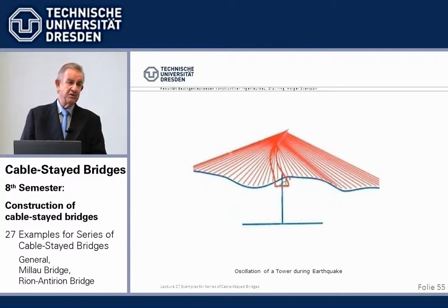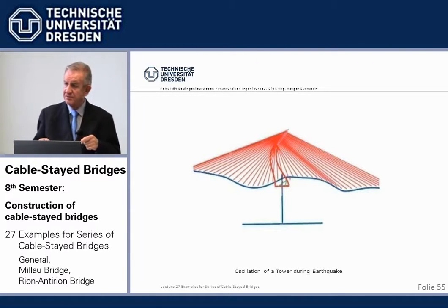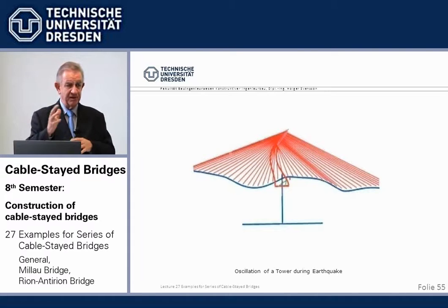Naturally, we have to look into the swinging tower. And that thing, depending on what frequency and accelerations we apply, oscillates in all directions and then has tension somewhere, which means cracked stage, which means less stiffness, which influences the eigenfrequency and the moments under a given deformation and all that.